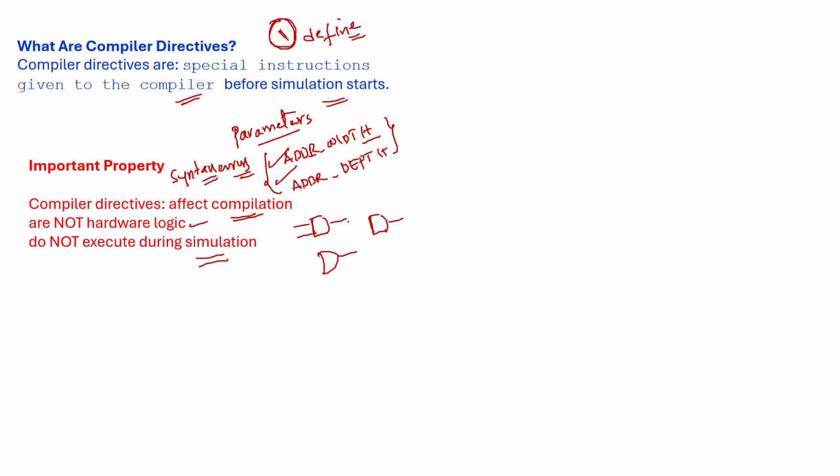For this hardware designing purpose, compiler directives are not involved in the hardware logic. They are available in compilation time only, and not available in simulation time.